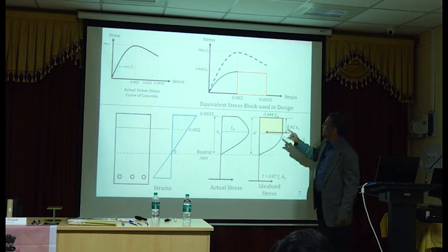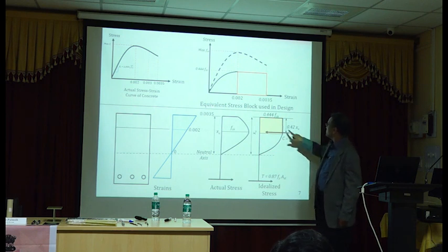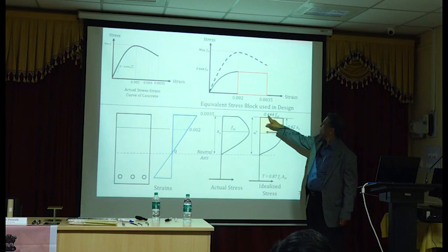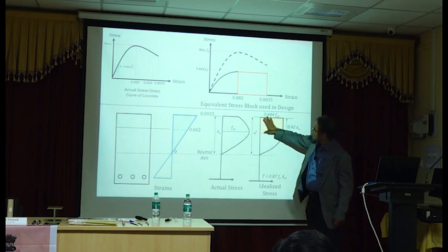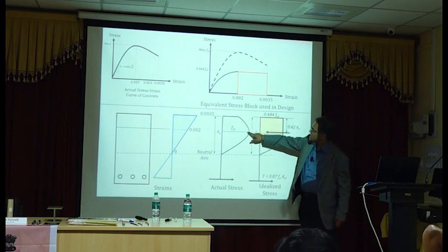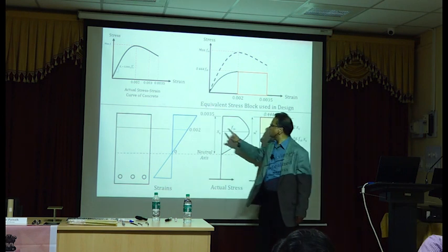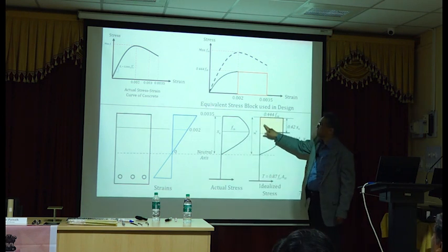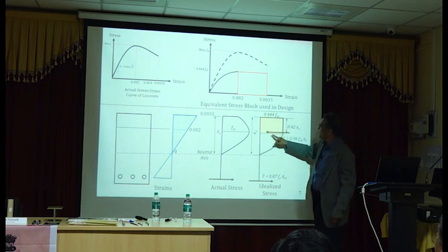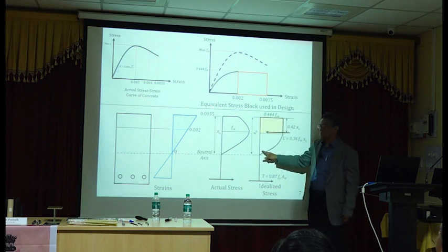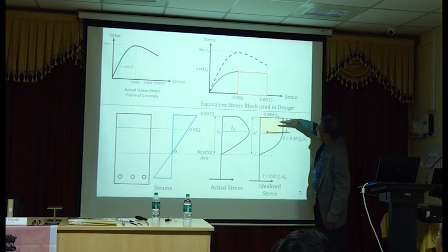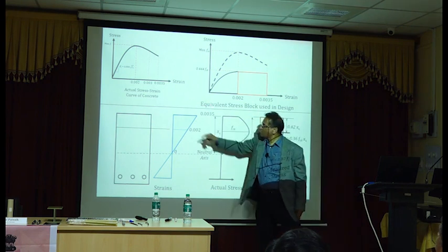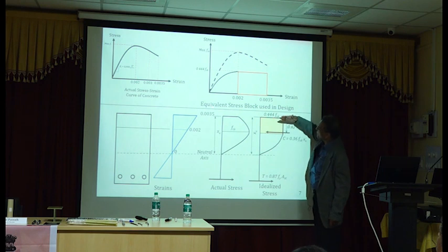Let's go back to the basics. This 0.36 FCK XU is based on this 0.44 FCK, and this uniform stress between this level here 0.002 and 0.0035, that's a constant value, right? That area is constant, and then this area is also constant. But now I am truncating depending on my maximum strain at the top fiber.